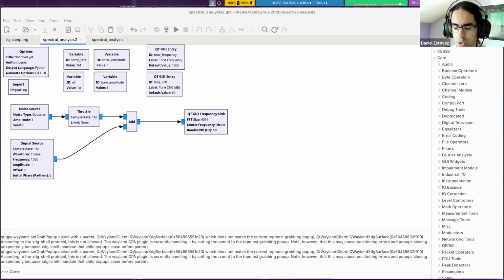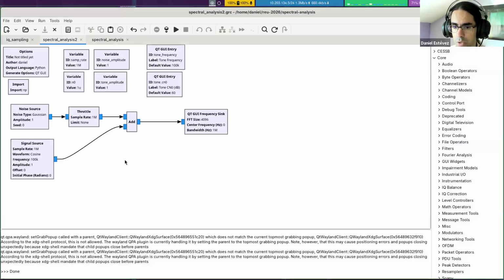So the next thing I'm going to show is how to generate a certain type of wideband signals, because there are definitely many types of wideband signals. On the previous tutorial, we saw another type of wideband signal, which is FM radio stations. That is analog FM modulation with an audio signal on a radio frequency signal. But what I'm going to show now is something more abstract, which is band limited noise. What I want to do is to generate noise, but so that it only occupies a certain portion of the spectrum, not all the spectrum as we did here.